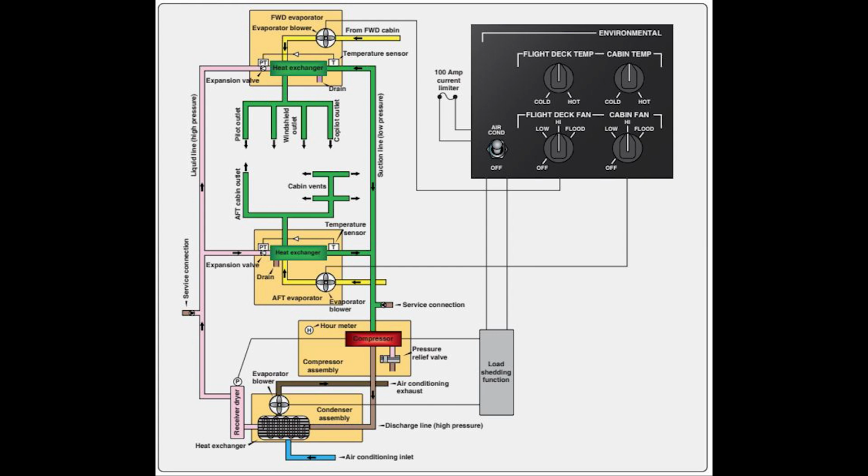Now, I'll tell you that you won't see a true blue air conditioner on a heavy commercial aircraft, generally speaking. These are going to be more for your business jets, where they have to get the aircraft running and prep it to receive passengers before they crank the engines.